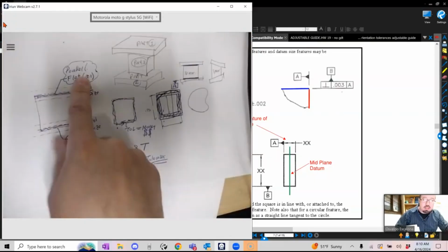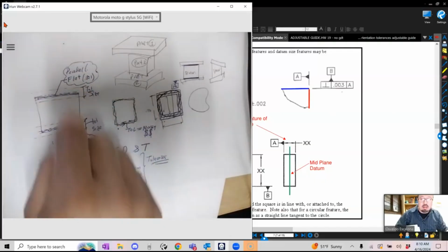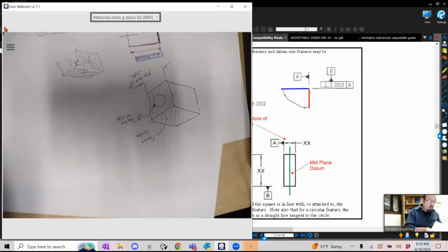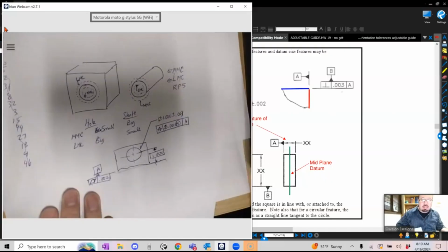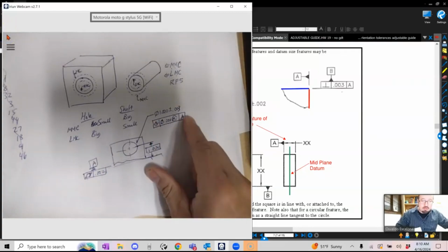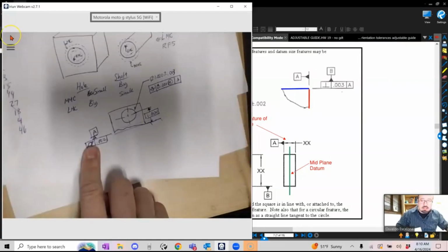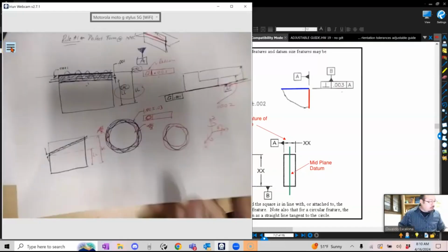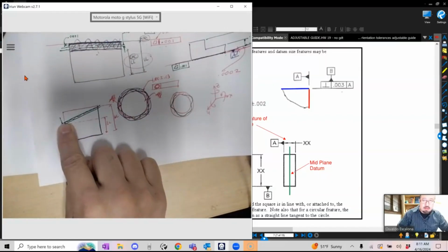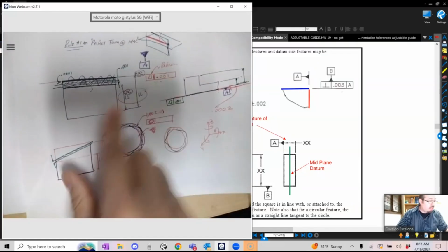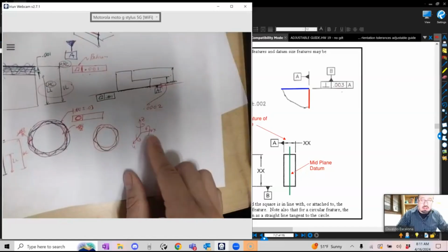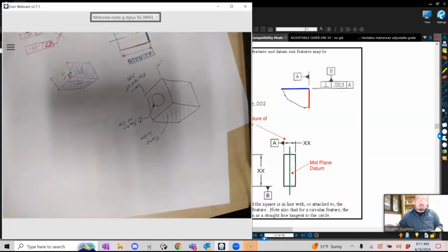We talked about notes that you can actually add to the drawing, by saying there is a well-established language, and that language is GD&T, geometric dimensioning and tolerancing. We talked about MMC and LMC, the maximum material condition. We talked about how we call out the datum. We talked about the feature control frame. This box is called the feature control frame. We talked about flatness, if I recall correctly, that it has to live within two parallel planes, spaced apart based on whatever the feature control frame tells me, and they have to live within your upper limit and your lower limit. We also talked about the degrees of freedom. You have three translations and three rotations on your part, and I believe that will end it.